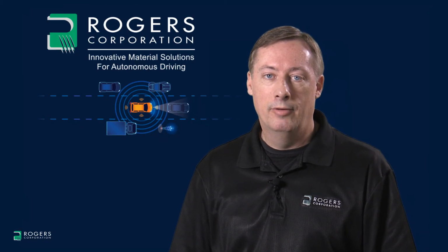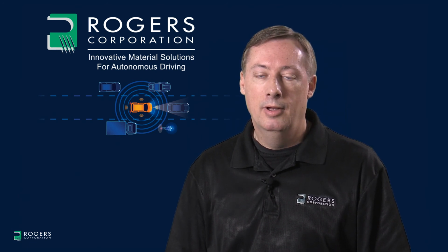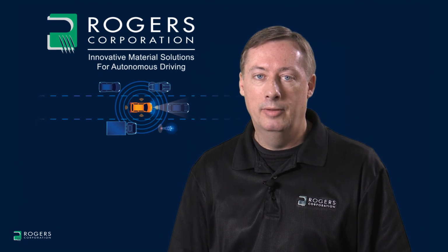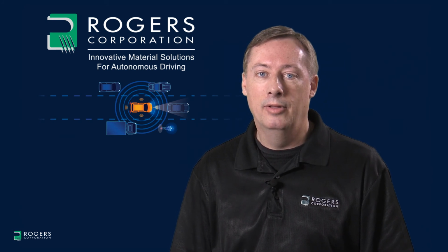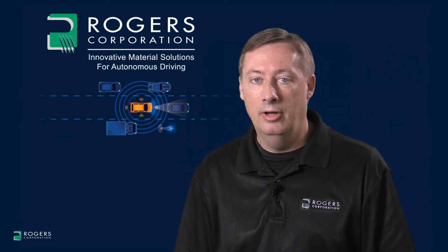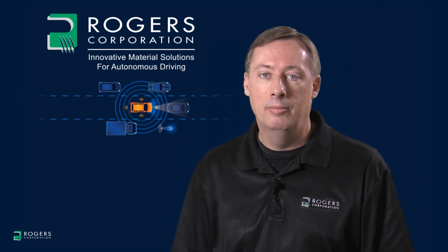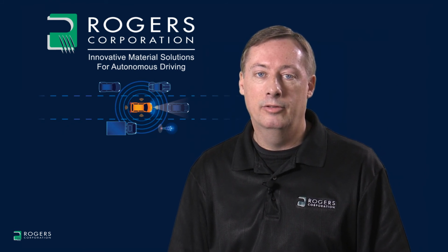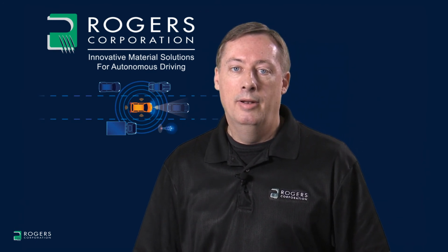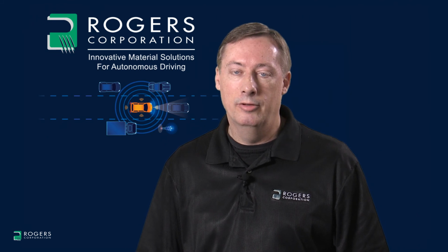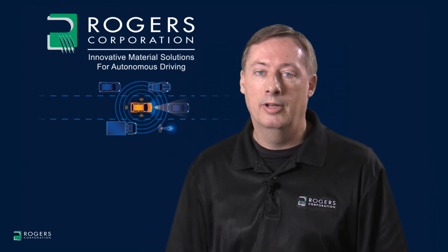For 77 gigahertz automotive radar applications, they're very commonly using thin circuits or thin substrates, and that's really necessary for several reasons. When you get to the millimeter wave frequencies, there are different issues, and a thinner circuit will allow you to have better RF performance. That's because the thinner circuit has less radiation loss. Also, a thinner circuit will be less likely to have spurious wave propagation modes, and you can have fewer problems with unwanted resonances. So a thinner circuit basically allows the designer to have more consistent RF performance at millimeter wave. Now, a thin circuit is also more sensitive to copper surface roughness, of course, and for a thinner circuit used at millimeter wave, the type of copper used should be considered very closely.